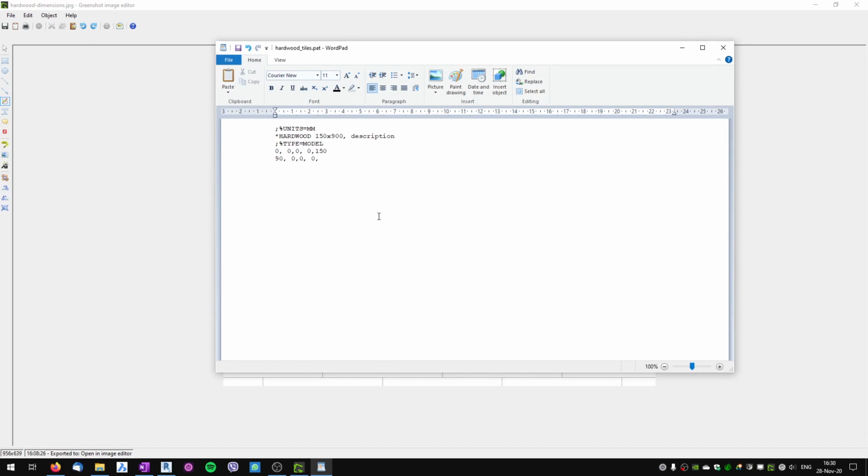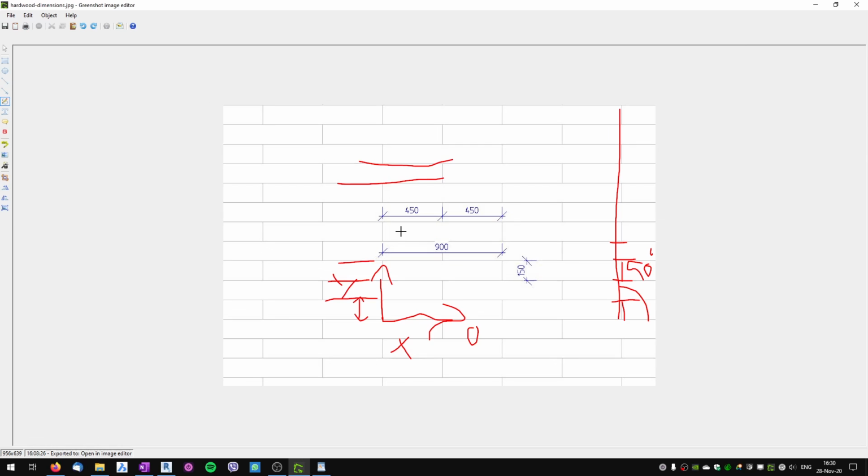millimeters. So it's 900. But now we have to also write comma, and we have to create the definition of the dashed lines. 150 and then 150 space. So to create the dashed lines, you write the number, the length of the dash, and then when you write with minus, it makes the empty space.